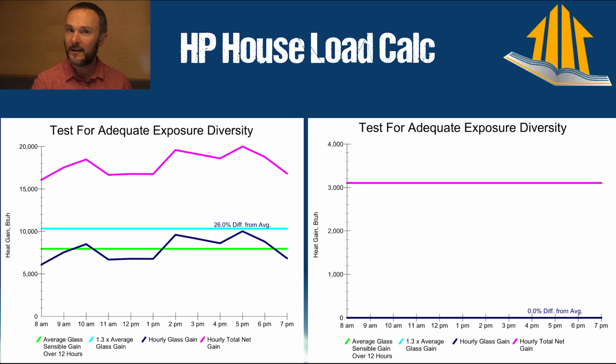What the difference is going to be is what we do in that space. So if I have a dance party in there, this is going to go off the charts, and I have modeled it with 15 people in that space, and I've done all that calculation. As you could see in the previous one, we had about a 1/4 ton of load. I'm going to be installing a 3/4 ton system in there, so that I've got it triple oversized, but it's an inverter system, which means it can dial all the way down to meet my very minimum needs in shoulder seasons. Shoulder season is when the temperature outside is mild.